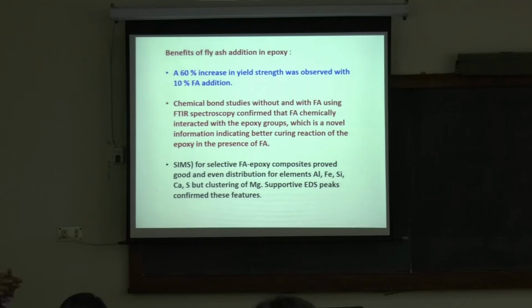And if you have clustering, it means there may be more particles bonded there, and that can initiate some cracks. If you have more clustering, because they become more combination of these ceramic particles, so it's much more brittle. So the cracks may start there, and once the crack starts, then the stress comes down. All right?